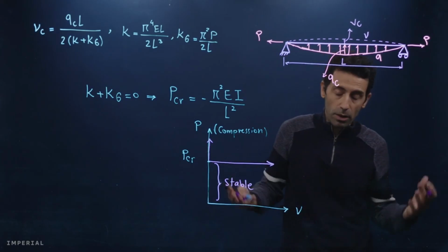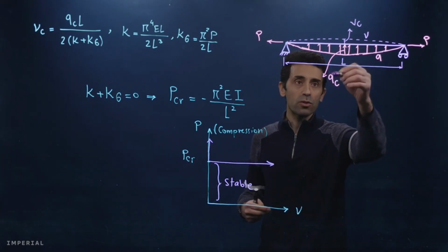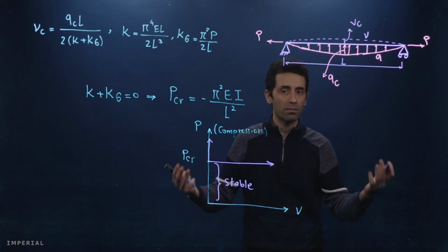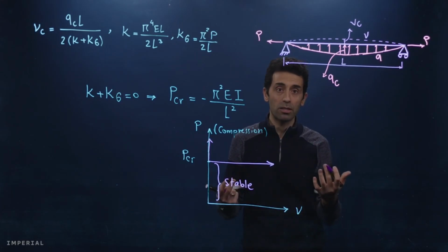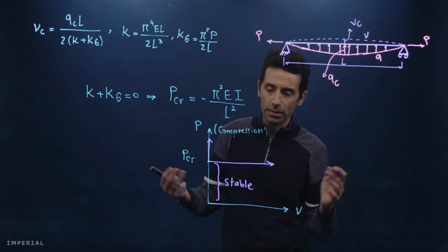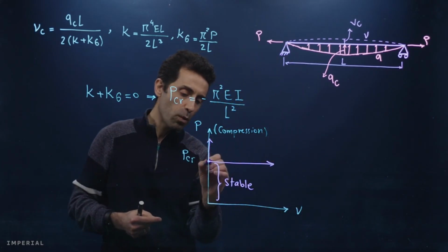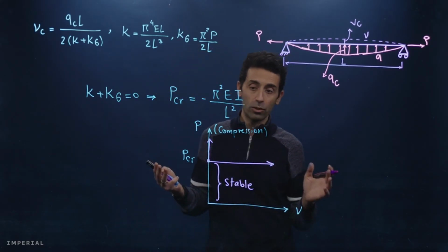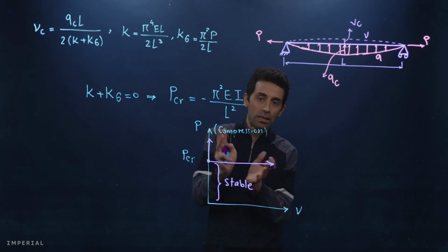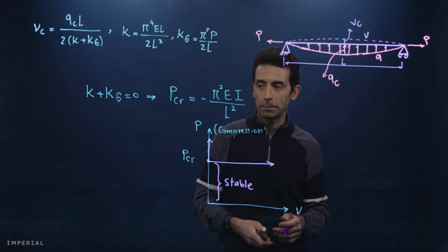And well, often in real world conditions, we don't have a perfect structure. Always we have some sort of disturbance in the structure, maybe a small lateral force, wind, something else, or imperfections in the material itself. So buckling is very, very likely in real world structures. And this is where this is happening. So this point where our structure has to decide which way it should go is called the bifurcation point. So bifurcation means branching. At this point, it can really branch, and most likely it will branch towards buckling.